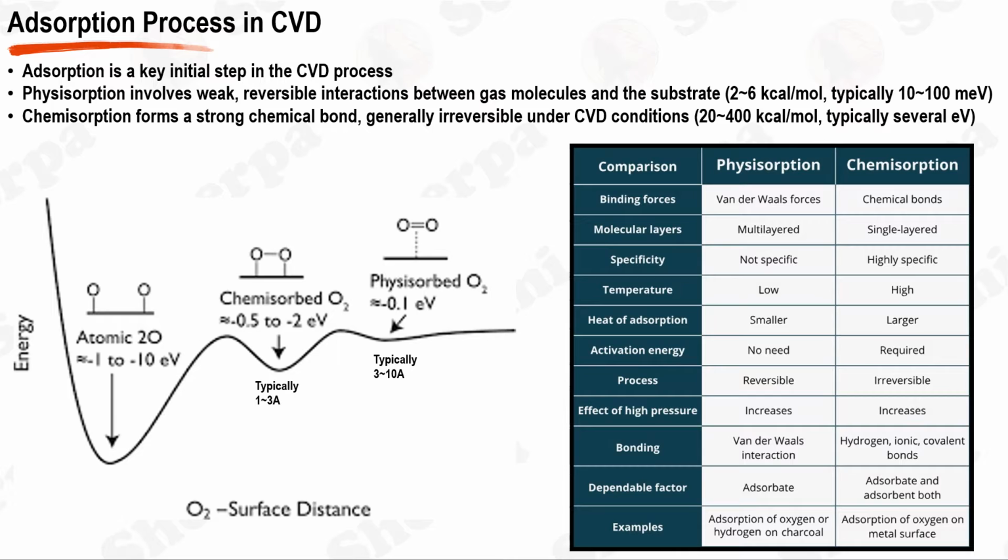Chemisorption can occur either through direct dissociation, where the gas molecules break apart upon hitting the surface, or through precursor-mediated chemisorption, where a precursor molecule first adsorbs onto the surface and subsequently reacts to form the desired deposition material. Interestingly, the transformation of gaseous species to atomic bonds on the substrate surface during CVD can proceed via various pathways. This could involve a stepwise transformation from physisorption to chemisorption and finally to atomic bonding, a more direct transformation from chemisorption to atomic bonding, or even directly forming atomic bonds.